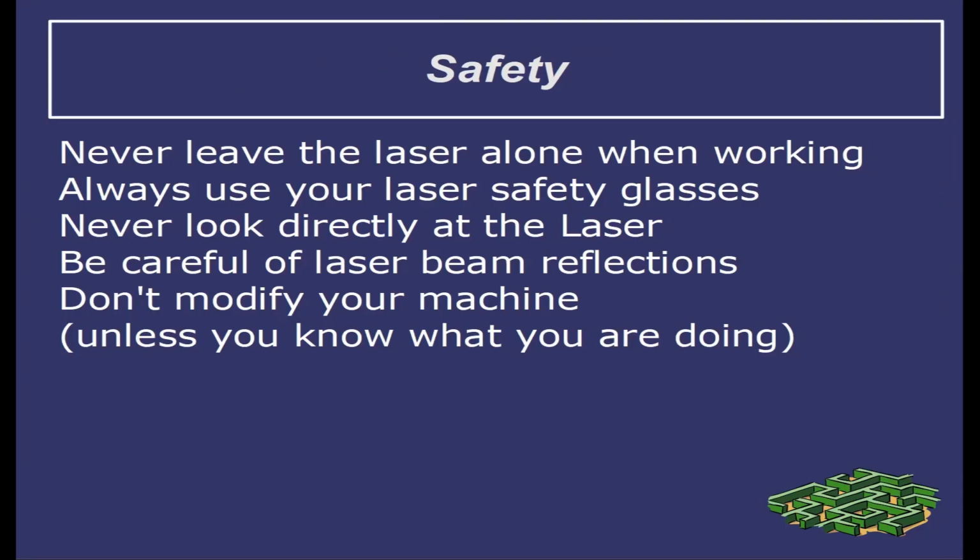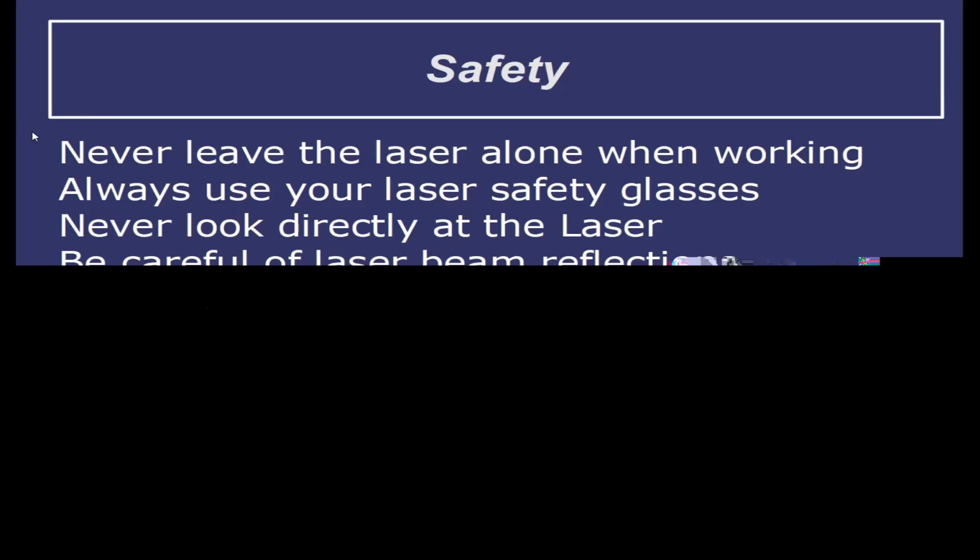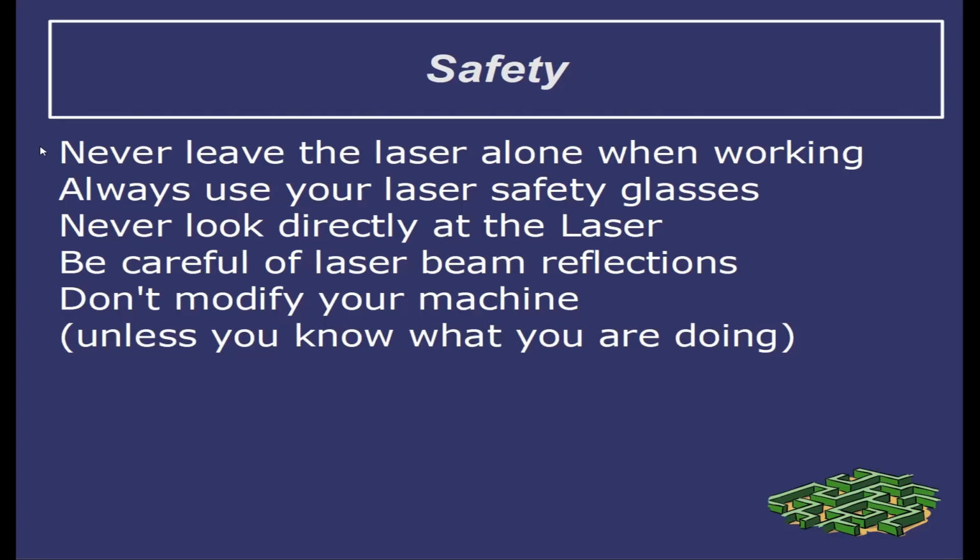Safety, very, very important. We stress this. These lasers are dangerous, very dangerous. You can blind yourself. You can set your house on fire, or your garage, or wherever it is you've got it. So never leave the laser alone when it's working. Always use the safety glasses that come with the laser, because the different lasers have slightly different wavelengths. Your glasses are for your laser.